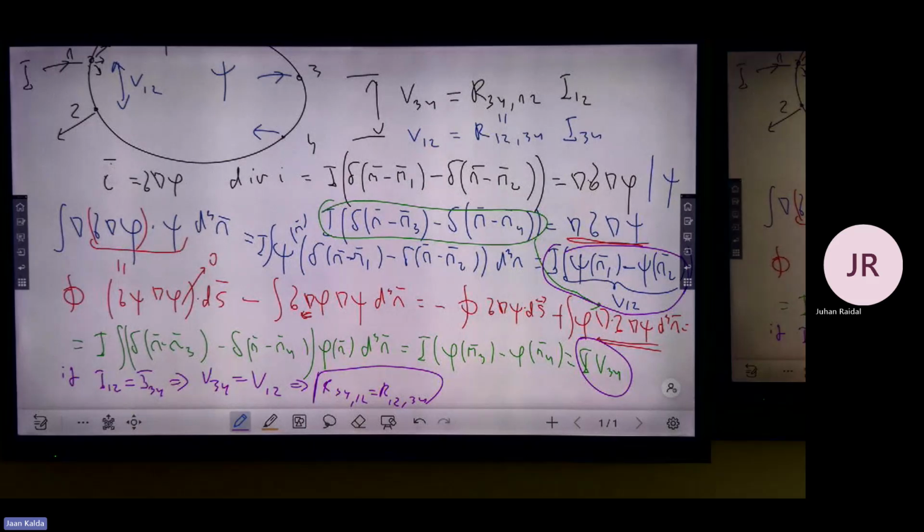If you have a coil, you have the total flux through that coil, but you need to keep in mind that because the coil has many loops and each flux goes N times through the loop, you need to multiply by the number of times it goes through. The coefficient of proportionality between flux and current, that's inductance.